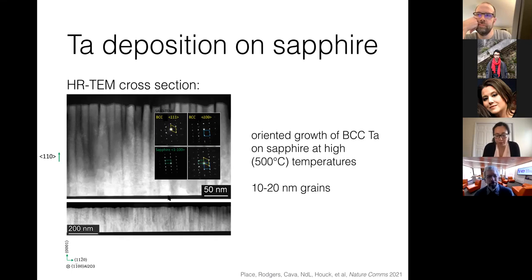So in general, no. The main reason is that there is no heteroepitaxial growth for diamond. It has a very tiny lattice constant, so it doesn't really grow on anything and nothing grows on it. The other big issue is that naively, if you want to make a passivation layer, you want the conduction band and the valence band to be around the conduction band and valence band of the material that you're trying to passivate.